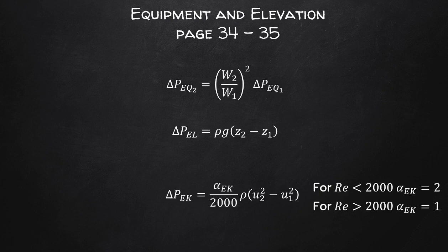It should, however, be noted, as I've said before, that since kinetic energy drops through pipelines are so small compared to other terms, we generally assume this effect to be negligible within pipelines. However, just remember that when you have flow that is arresting itself as it reaches a vessel, then we can do these sorts of kinetic energy calculations.